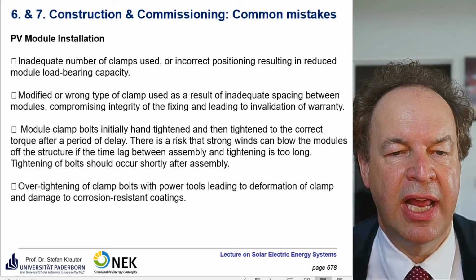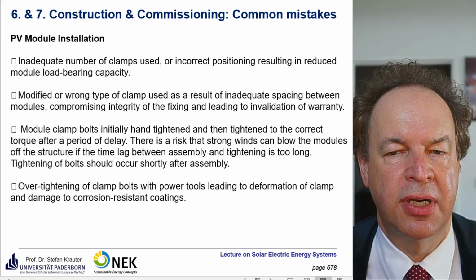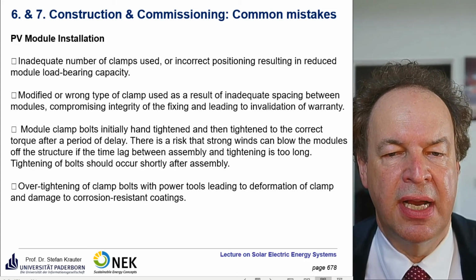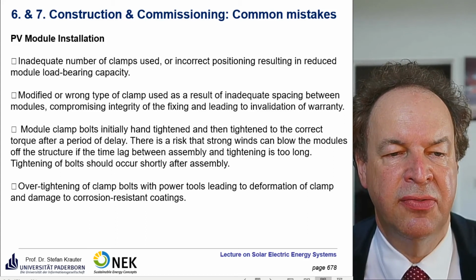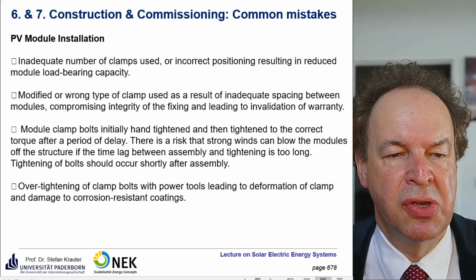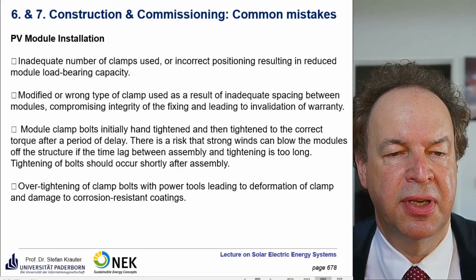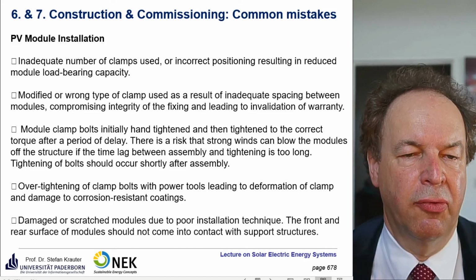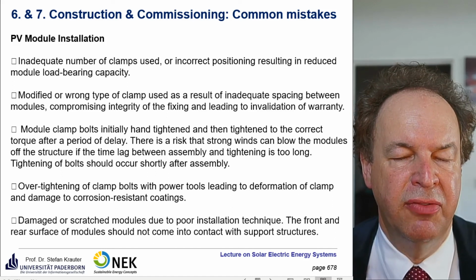Over-tightening of clamps. Some installers don't have torque-limiting tools, and they may destroy the clamp or even damage the modules. So, for example, the coatings of the clamp, but maybe even of the module.